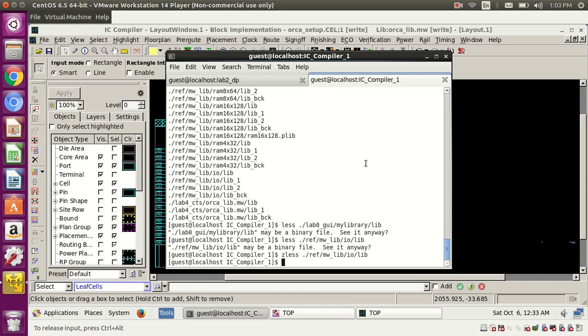This input is changing every clock cycle, or assume for some 10 clock cycles. But whenever it is 0, all these inputs will remain the same, so the output should remain the same. So we don't need to give it every clock cycle; the output is already there, and we are giving the same output from D to Q for every clock cycle. So instead of doing that, if we switch off that flop for some time, then that many clock cycles will be saved. Now, what is the flop doing?